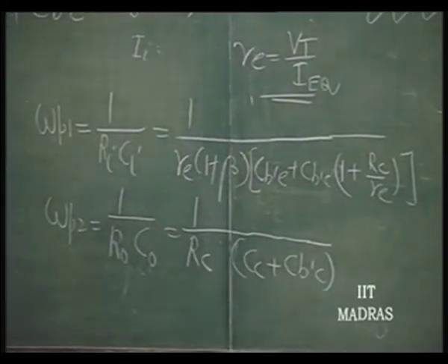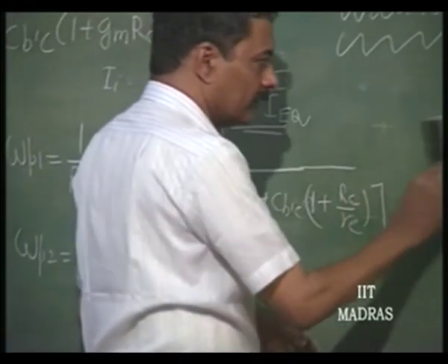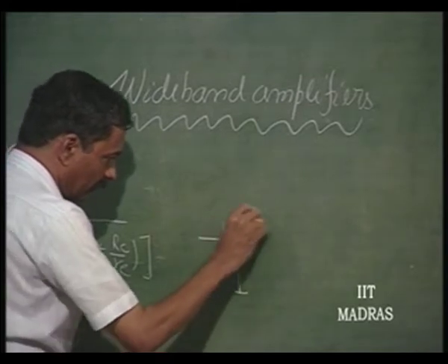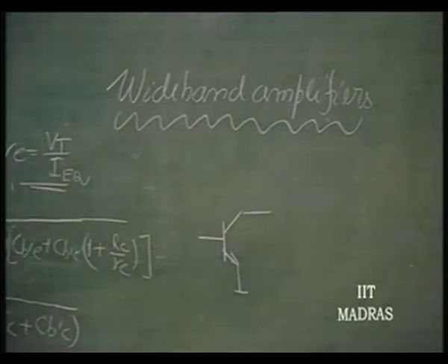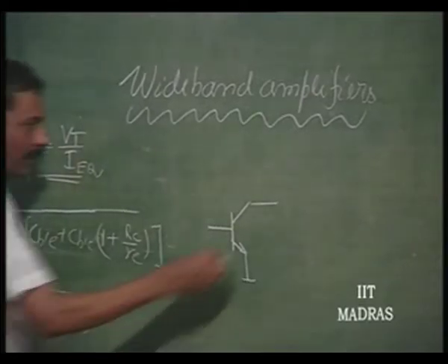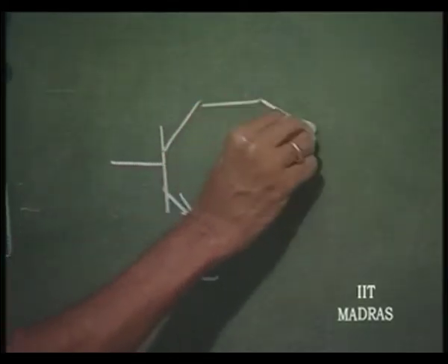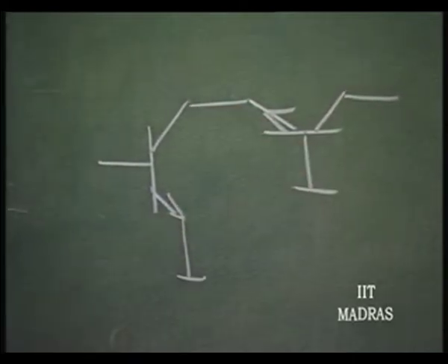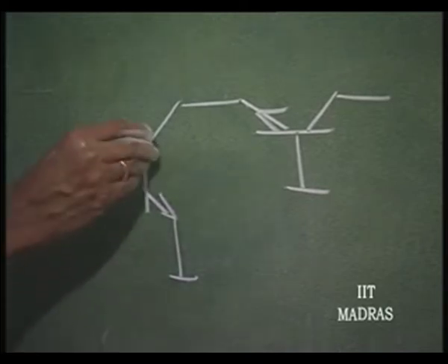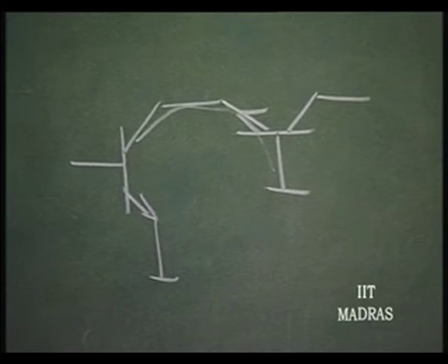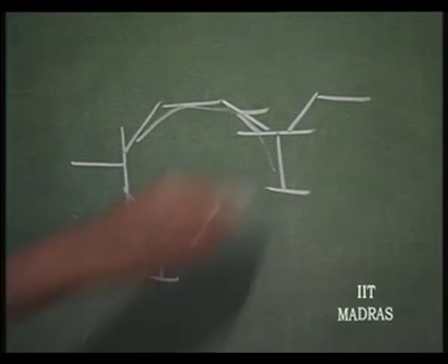For that purpose, what I do is, this common emitter amplifier, let it have low voltage gain. So, what do I do? I will now feed this into another common base structure. This is a common base structure. So, this current is going to be going into the common base structure input current. So, output current is same as this.